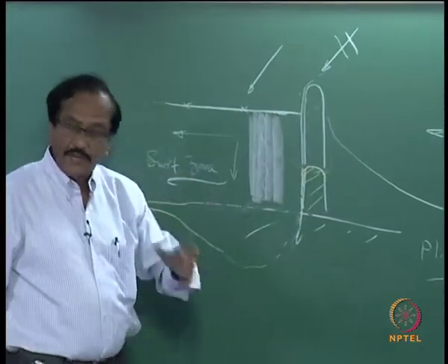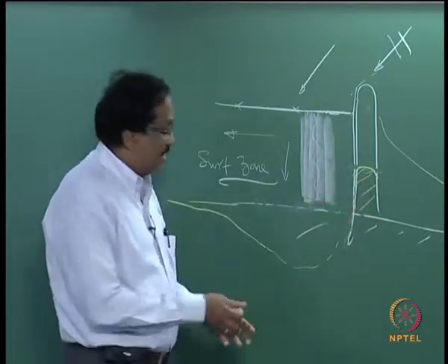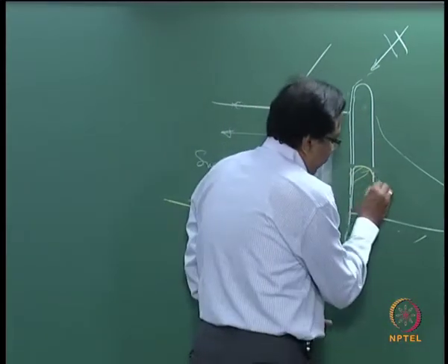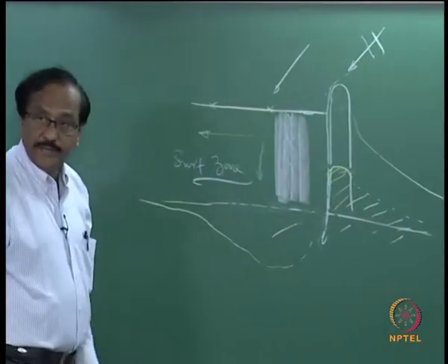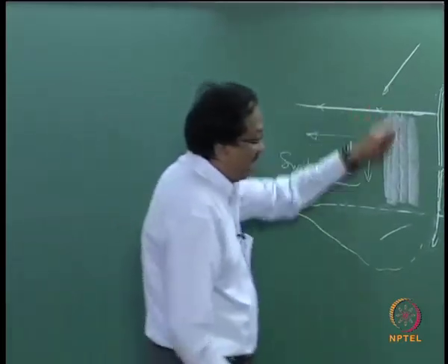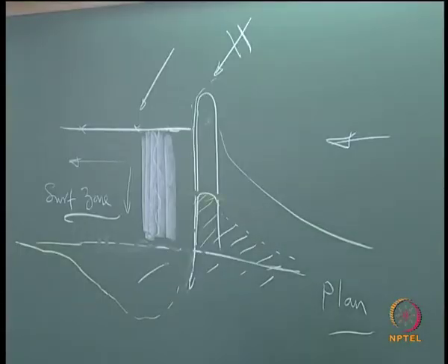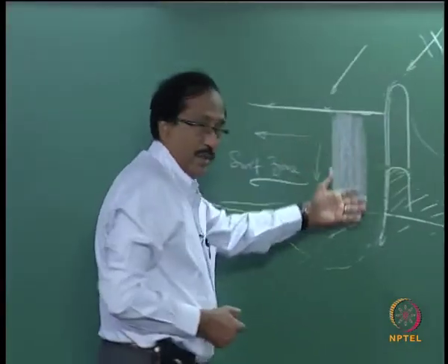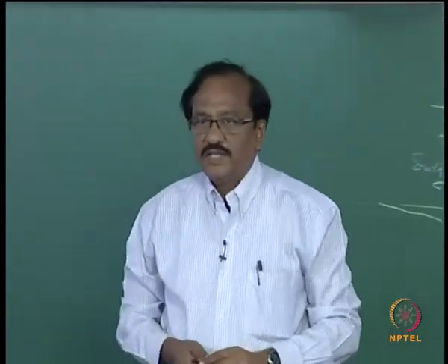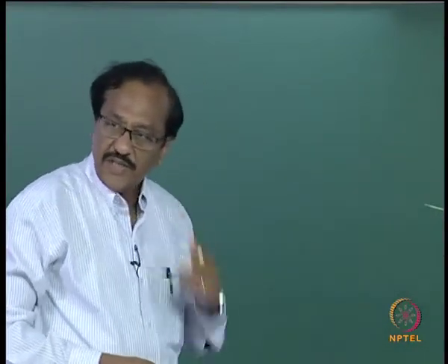But you have the options of having a long groin or a short groin. If you have a short groin, the deposition, the advancement of the shoreline will be something like this, am I right? Suppose you have a long groin, you are going to have a wider beach. What exactly would you like to have? You would like to have a wider beach, etc. All these things, and how much you can invest on this, have to be considered before you really go in for the planning of the construction of the groins.